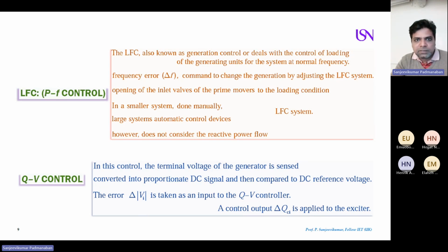So a synchronous machine can work as an over-excited generator, an under-excited generator, and a normally excited generator. In the normally excited mode, it will work as a synchronous generator. It delivers constant voltage. Of course, you can have a unity power factor, but you can also store energy like a capacitor. So when there is reactive power, we can use a synchronous generator in parallel in our power system. Obviously, it is widely used. We will see some examples later where your synchronous generator can work as a reactive power controller. They store all the reactive power generated from your power system, and of course, the stored energy can be delivered back to the grid. That is the advantage of using a synchronous generator.